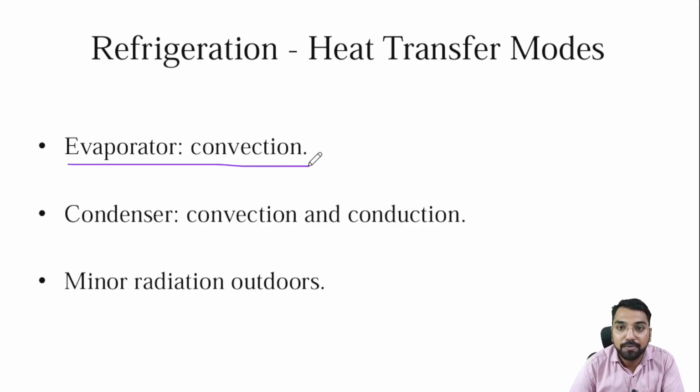The evaporator is a part of refrigeration where the evaporation takes place and heat is absorbed from the surroundings. In the evaporator, the surrounding is at a higher temperature, and the evaporator is where the liquid refrigerant flows. As I said, heat always flows from a higher energy level, that is higher temperature, to lower temperature, by the second law of thermodynamics. So in the evaporator the heat transfers from the higher temperature to the evaporator, which is at lower temperature, by virtue of convection heat transfer.